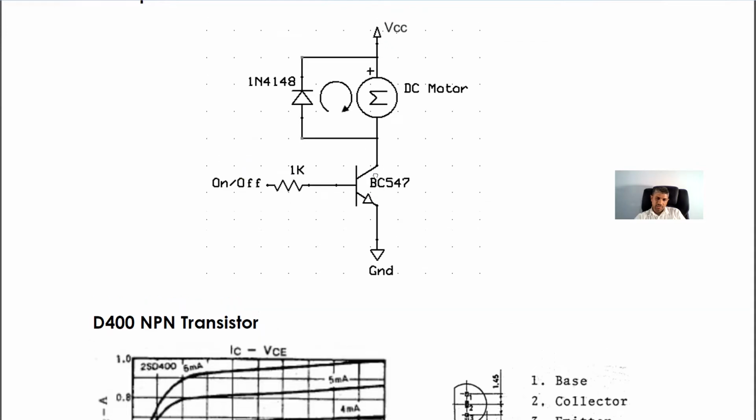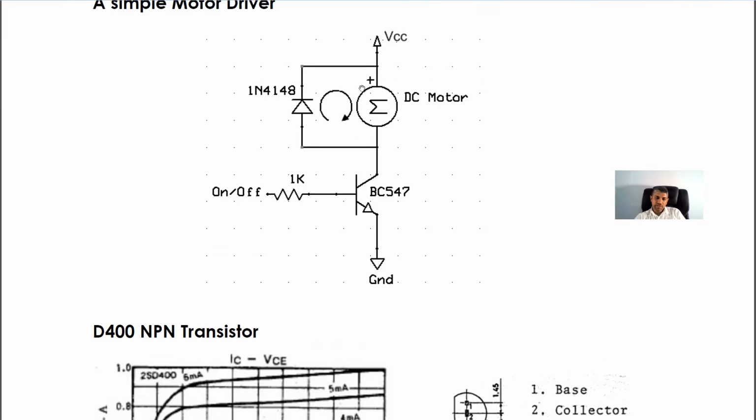But sometimes the motor will not rotate, because the current is not enough. The other thing is that the transistor will reach a very high temperature due to the higher current flow. If the current becomes relatively higher, then the transistor will immediately burn. Therefore, it is better to use a different transistor.